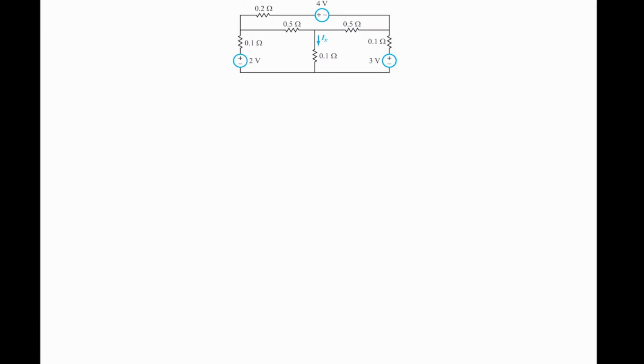In today's problem, we're going to use nodal analysis to find the current Ix. As always, we pick a terminal that connects the most branches and apply KCL at that point, and call the equations we generate at that point a node equation because it's a node. In this case, we want to find Ix, so we can choose the terminal above Ix.